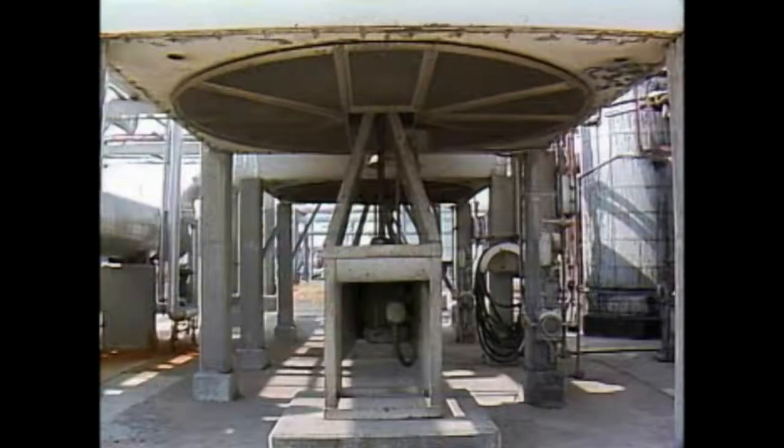The fluid transfers heat to the tubes by conduction and convection. Some of this heat is then transferred through the tubes and into the fins by conduction. From there, heat in the tubes and the fins is transferred by conduction and convection to the surrounding air. To increase the amount of heat transferred to the air, the fans in the cooler can be started. This increases the airflow through the cooler, which increases the amount of heat that is transferred by convection to the surrounding air.